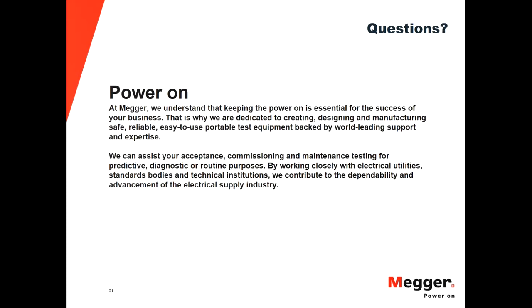So yes, the charger can be used to support the substation or the facility when the battery is not there, but then you're risking that if there's any power failure, you're going to lose the charger and you're going to lose the facility because there's no battery to support it. So that's when the need for the backup battery comes in, depending on the criticality of your installation, or if you definitely cannot have the load without any power, you don't want to risk that. So you want to install a temporary backup.